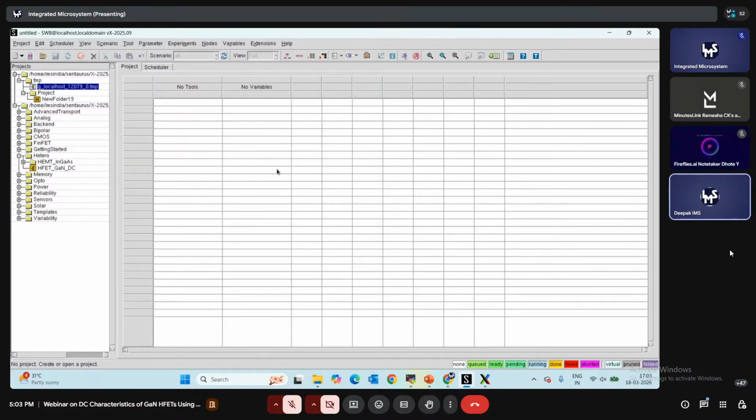In that case, we actually have the contact code. You define the resistance and the work function itself. In TCAD, you cannot do such kinds of things. You just take those values and define them in the contact. For defining the work function, which material do we have to take, the uppermost? For that, since you are using titanium, it would make a titanium nitride itself.